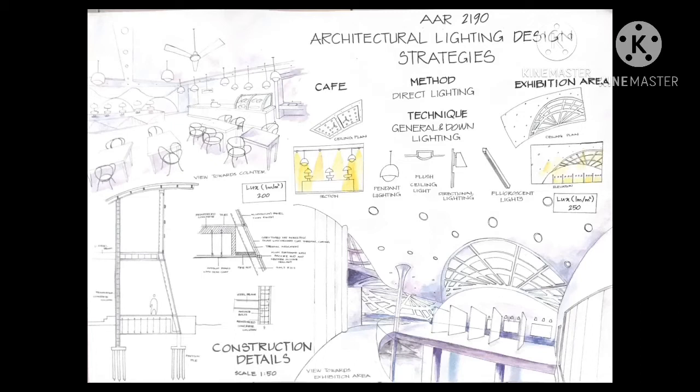But there is also directional lighting mounted on the wall to spotlight the posters on the wall to ease people to read. The lamp for the directional lighting is a halogen lamp. Halogen lamps have been widely used in exhibition areas because of the chromatic quality of their light. Halogen lamps typically have a color temperature between 2800 and 3000 Kelvin and a natural spectral distribution that make them ideal to illuminate posters, paintings, etc. And there is also the flush ceiling light as the light source during nighttime.